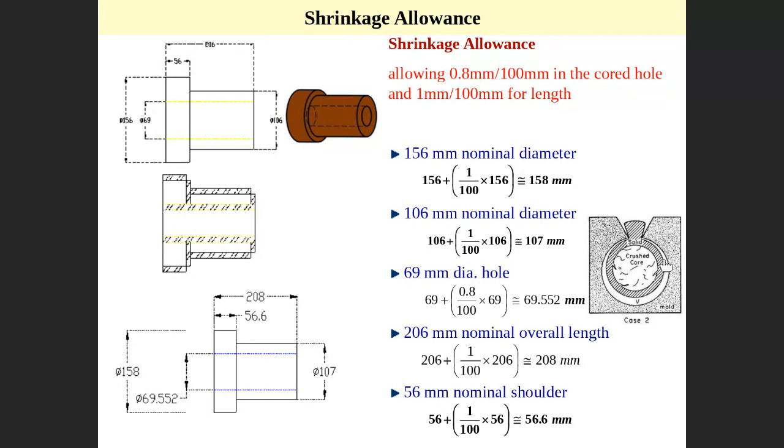Then if you see the shrinkage here, the material will shrink. All dimensions are getting smaller, whether internal dimension or external dimension. So all external dimensions and all internal dimensions will get smaller. Getting smaller, then we need to increase. We need to add it.